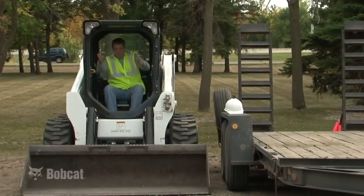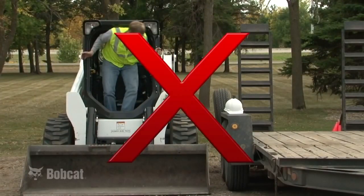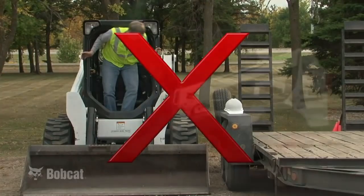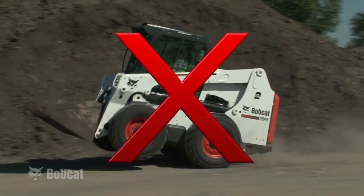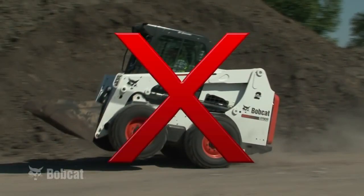Never stand, lean, or reach out of the front of the loader when the engine is running. A steering control or hydraulic control could be activated. Don't make any sudden stops, starts, or turns. Again, operate the controls smoothly.